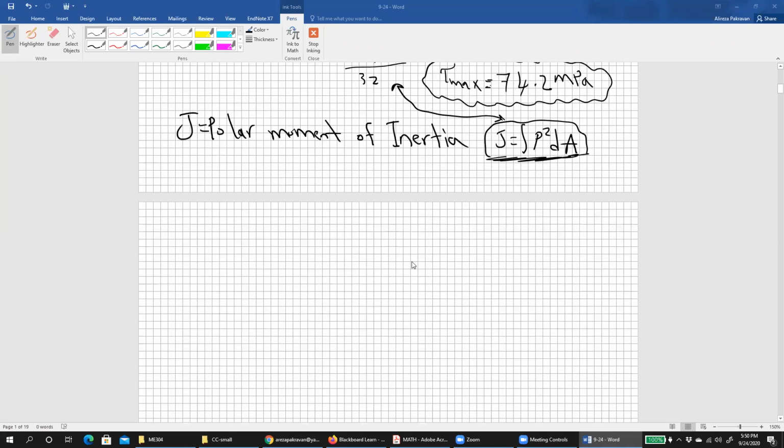But if you remember in the last lecture, we said another important parameter in the torsion chapter is the angle of twist, right? We show the angle of the twist phi on the section, and it plays a role similar to the elongation on the axial bar. In the axial bar, we have a normal stress and then elongation, but in the shaft, we have a torque, and the deformation is shown based on the angle of twist, right?